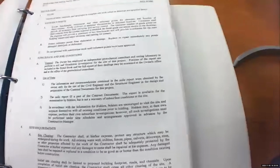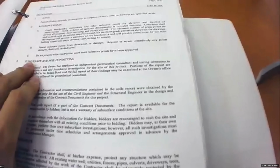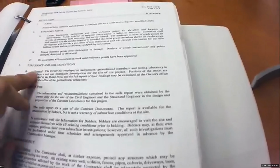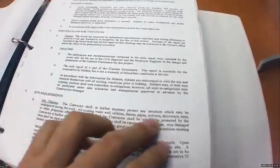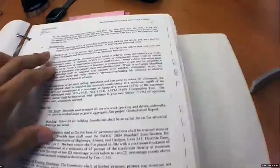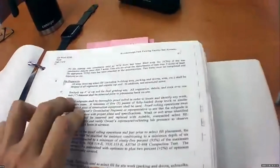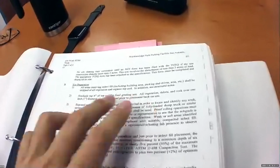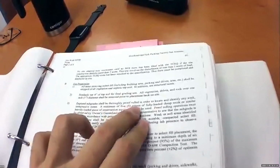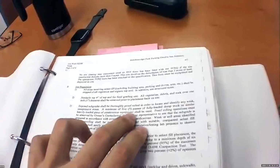For example, you have to follow certain ASTM standards. Then you have to set them here, or we need to follow this one. Subsurface and soil condition, so general use of data, site requirements. So basically, site clearing means what? Site preparation means what? And actually, it shows a lot of details, such as stockpile the top 4 inch of topsoil for final grading use, and shows that a minimum of 5 passes of a fully loaded dump truck or similar heavily loaded pieces of construction equipment should be used.